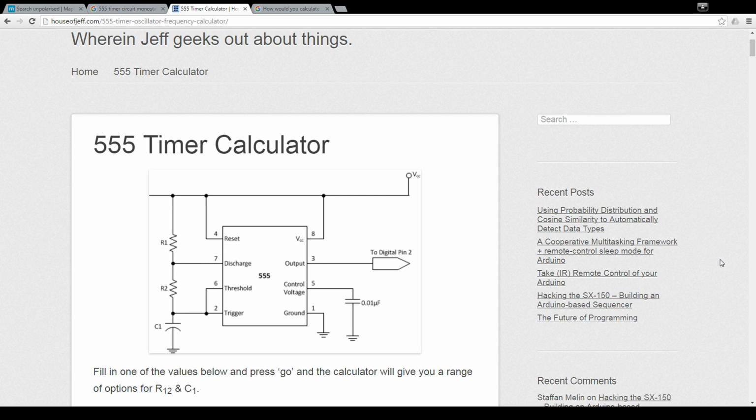You see a lot of people asking how do I get two or more inputs to essentially turn into one input without using the Arduino itself. The easiest way would be with a diode, but when you're working on 3.3 volts logic, that can be a bit iffy, because it falls into a grey zone between logic high and logic low, and it doesn't have a clear 0 volts or 3.3 volts in this case.